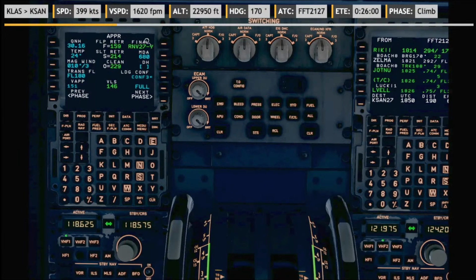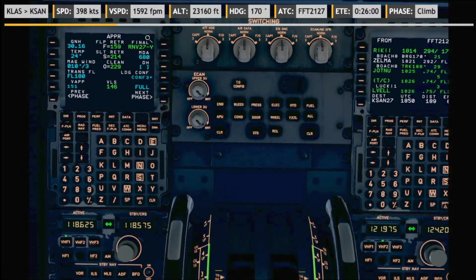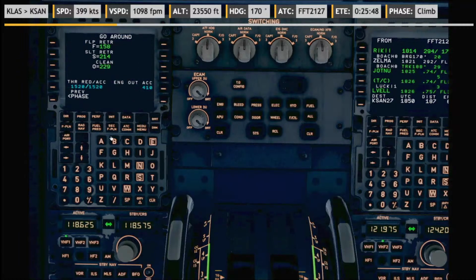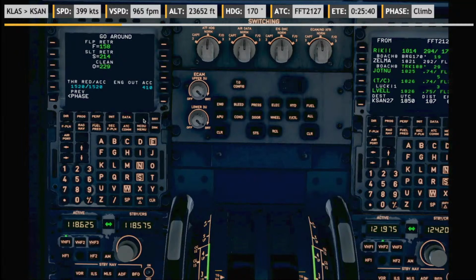Compared to minimums for an ILS decision height, it's a minimum descent altitude for our non-precision approach. It's very important. It's also not a CDFA approach. And I don't think we can do this one CDFA because it's not published. We are going to do it as published to make everything easier. And then on the go around, this makes sense. Our engine out is going to be, missed approach is 2500, so we want 2500 up here as well.